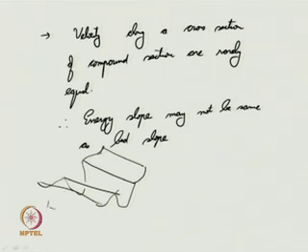You are going to take the stretch or reach of the channel, you have to do certain averaging along the reach and then try to evaluate the discharge. Let us go through them. So, for such a type of figure, you now require to take the energy slope rather than the bed slope.